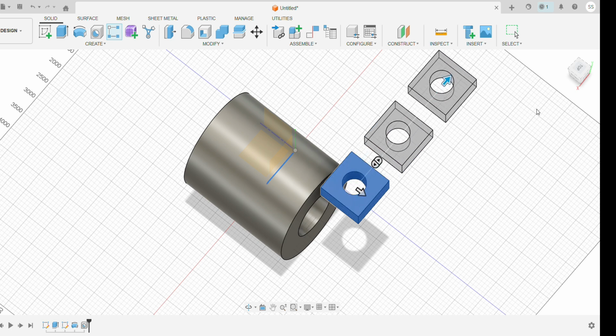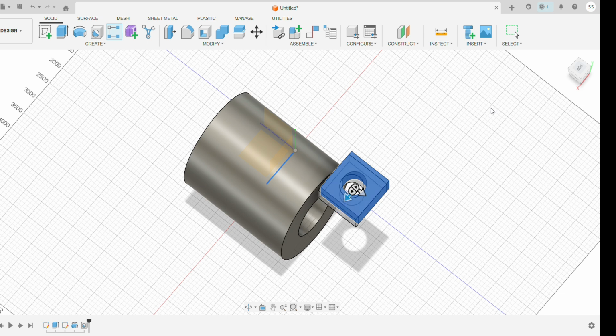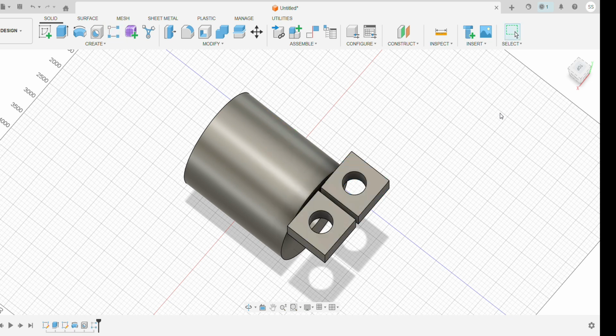And this is the pattern option. This is the rectangular pattern. There are 2 to 3 kinds of patterns. The most common are rectangular and circular. This is the rectangular pattern, which goes along the X or Y axis, and you can see at some distance it is separated. You give the distance and the number of patterns. Say the pattern count is 2 and the distance is 1, and you get a pattern like this.